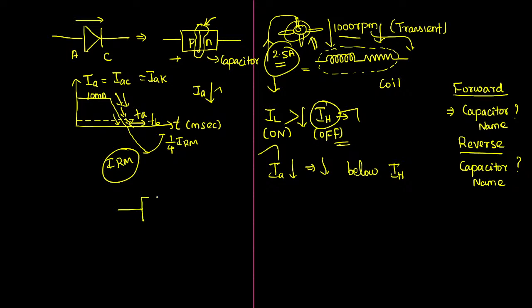We have seen in the diode also, the region called the reverse bias region. What is the meaning of reverse bias region? Basically when the diode is in forward bias, current flows from anode to cathode, and across the anode we inject positive voltage, across the cathode we inject negative voltage. This is when the diode is in forward bias or on state. It may be an SCR also, same process. Don't think too much. In the SCR one more terminal comes, that is called the gate pulse. Anyway, your question hasn't talked about the gate, so I'm just interlinking the SCR with the diode. Nothing will differ here. You can observe the same property for the SCR also.